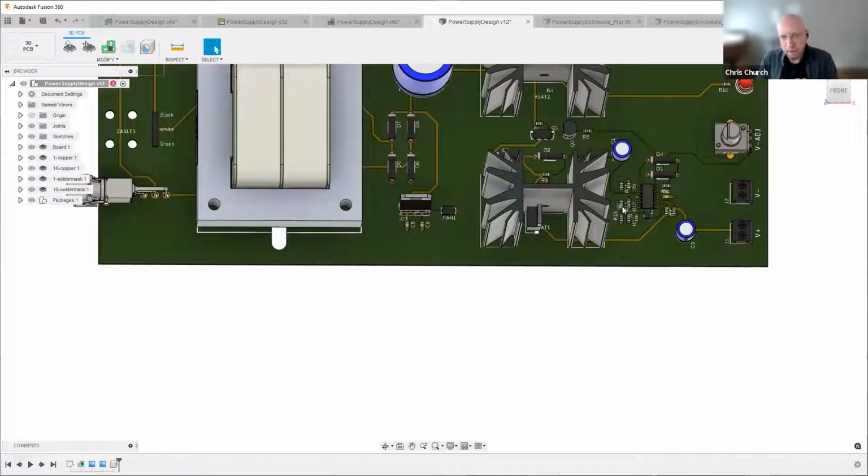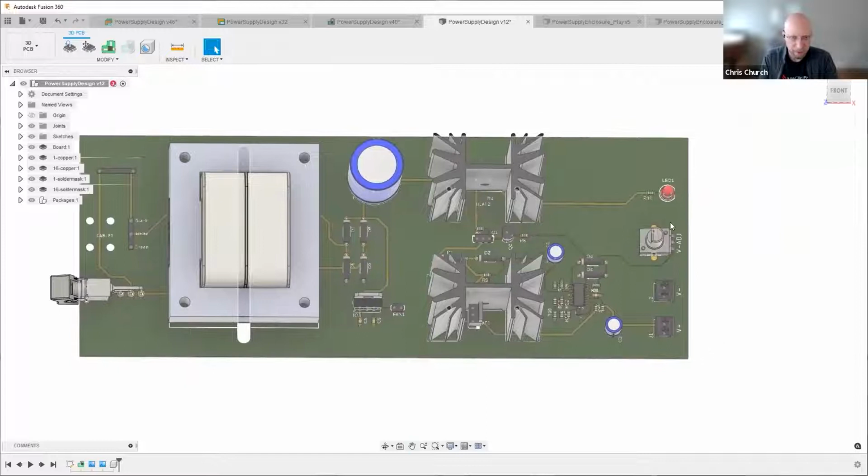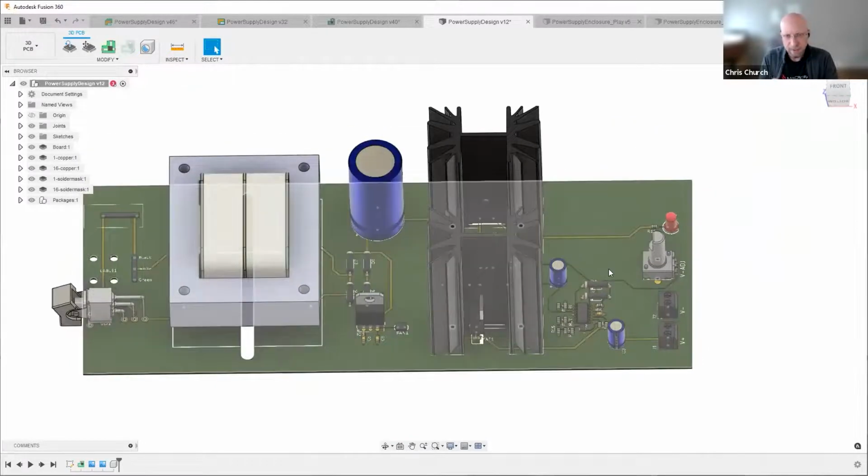So now, let's look at anything else there on that design. Now I see the LED. I see that you have it there flush. That makes it real easy to produce. What we'll see a lot of times is that the LED, and by this LED, I'm talking about this one right here. When we see these LEDs, a lot of times what we see is an interaction between an LED or some kind of control input and the enclosure itself. For example, you may want it bent at an angle and kind of stepped out and interacting, maybe pushing through the face of the enclosure.